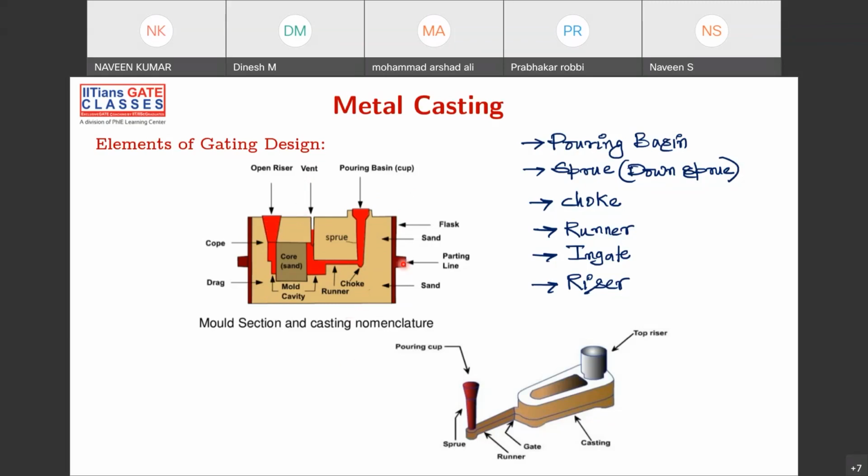Okay, fine. So once you're pouring, this is what your casting will look like. This is your main object, and here you discard this, this also you discard, and then this is your main casting object. These are getting solidified, but anyway you're discarding them. You are not pouring exactly the same amount of material that is required for casting. You're pouring extra material because it will solidify in the pouring cup, in the runner, and in the riser also. But at the end you'll be using only this part. This part is very important for you. The extra gating elements will be removed from the casting.